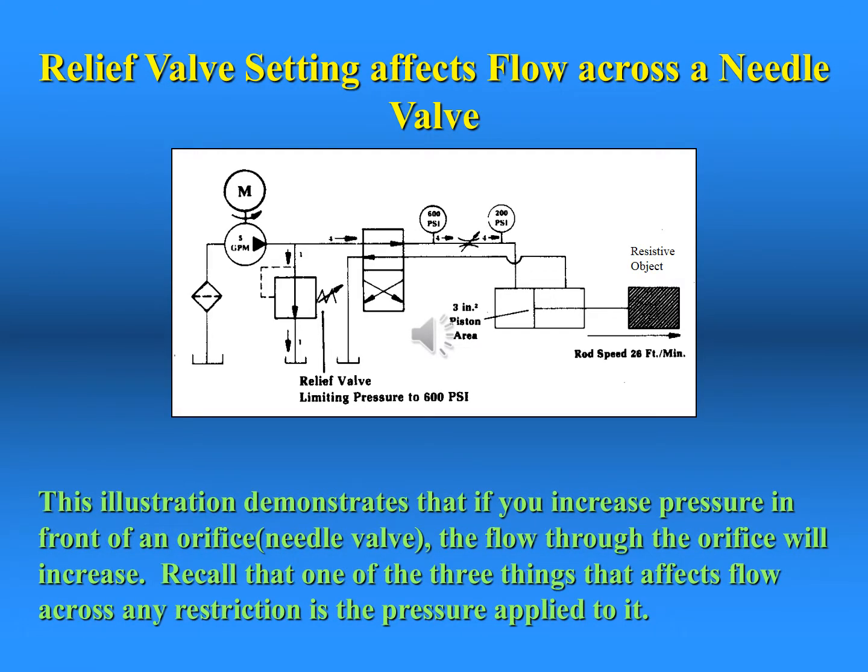Once the needle valve has been set, an increase of pressure at the relief valve will force more oil across the needle valve. This is like using a variable power supply in electricity to increase voltage over a resistor. This effect will be demonstrated in the lab.